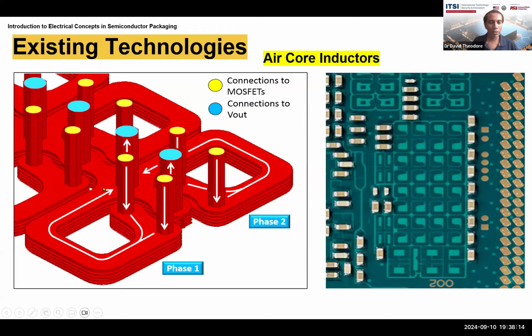So you have inductors here. Basically, it's like a coil of wire. When the voltage sends a current through this inductor and there is a change in this current, it creates a magnetic field, right? So first of all, if there is a current, you'll generate a magnetic field. That magnetic field stores a certain amount of magnetic energy. If you try to change the current, this magnetic energy will compensate for the change in current to resist the change. So basically, the bottom line is the inductor stores magnetic energy, which is translated into current flow if the current drops below some number. So that's what the inductor is.